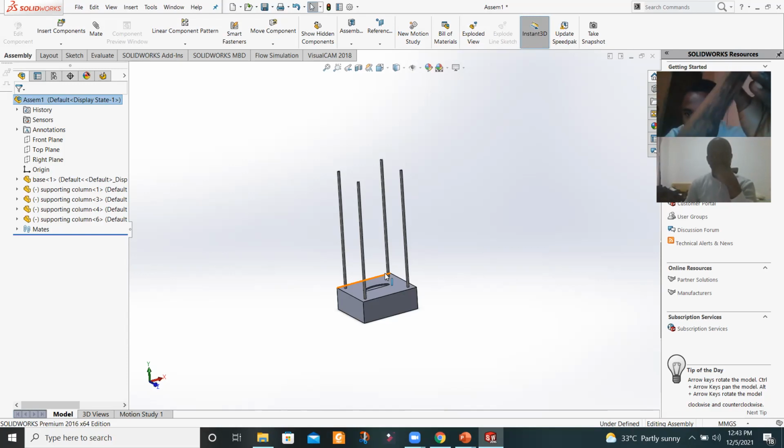So this is the metal base produced separately without the abrasive head. The aim of this machine is to ensure that the abrasive head is glued to the metal plate. The metal plate was cut by plasma cutting. This was done with oxyacetylene cutting. The aim of the machine is to gather biological agricultural waste and use it to make this brake shoe and the abrasive materials. Now, this is how the machine will work.